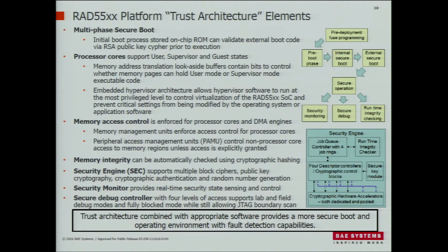There are a couple of other things I pointed out earlier with the hypervisor support in the processor, and being able to partition and have safety in that sense, and then the PAMUs with the I/O MMU, that kind of control. So this trust architecture is all the things that are implemented in the hardware that are trying to facilitate deploying a safe, secure application.